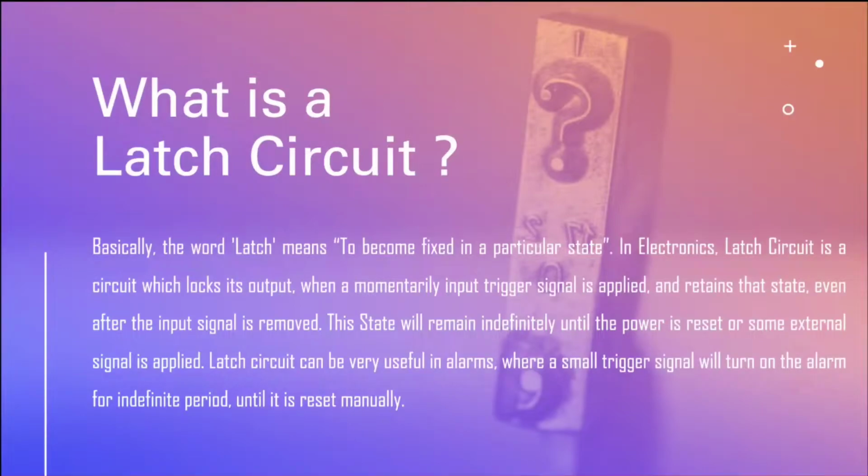In electronics, a latch circuit is a circuit which locks its output when a momentary input trigger signal is applied and retains that state even after the input signal is removed. The state will remain indefinitely until the power is reset or some external signal is applied. Latch circuits can be very useful in alarms, where a small trigger signal will turn on the alarm for an indefinite period until it is reset manually.